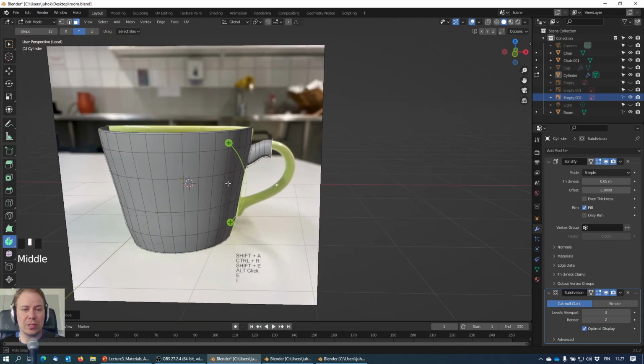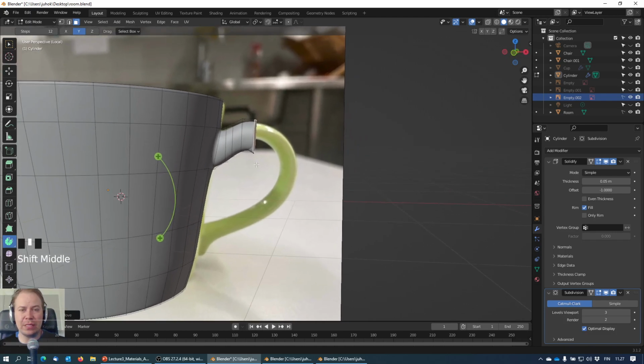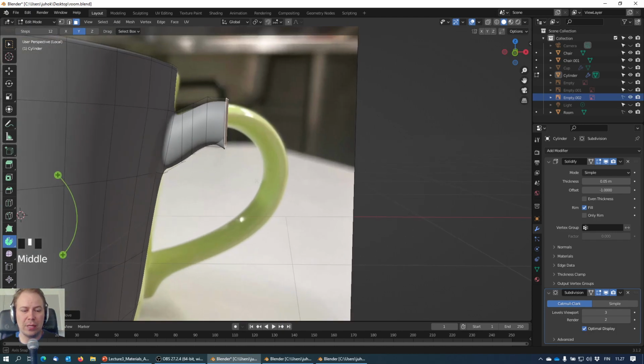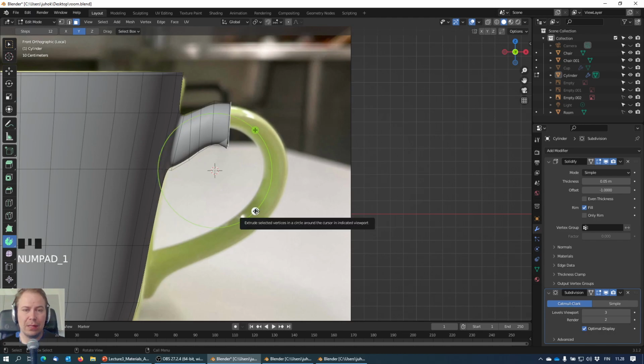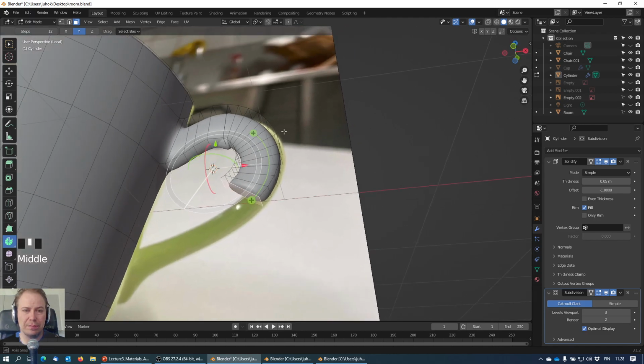The spin tool works like this: you need to put your 3D cursor where you want the spin to happen. So basically, if you want the spin to happen around here, you are not supposed to use it here. Shift right click somewhere here so the spinning possibility becomes active. Then make sure you have the Y axis selected so it spins on the right axis. In 3D you always need to remember that. And then basically you can spin it over.